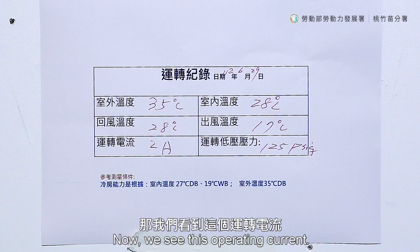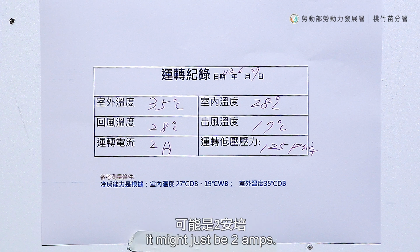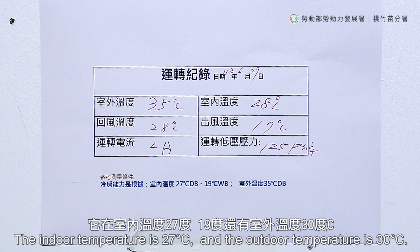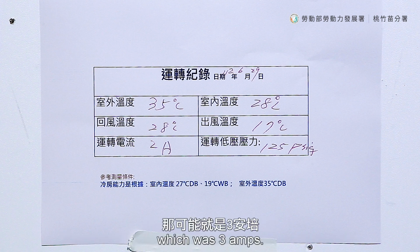Now we see this operating current. The operating current on the label may say 3 amps, but when the AC is running, it might just be 2 amps. That's because it was measured in a certain environment. The indoor temperature is 27 degrees and outdoor is 30 degrees. The operating current measured under such conditions was put on the nameplate, which was 3 amps. But it might just be 2 amps here.